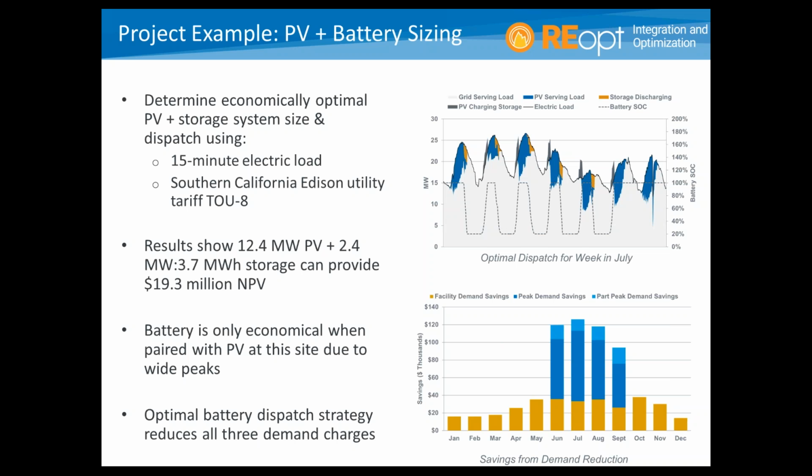So in this graph up here on the right, you can see that early in the day, PV is meeting a lot of the load on its own and can shave the peak on its own. But then later in the day over here on the right, the storage needs to fill in to continue that peak demand shaving. And so they're really effective together because PV can meet a lot of the demand for a lot of the day. As PV starts to trail off at the end of the day, the storage kind of fills in on the shoulder here. And so this is where we get the full peak shaving. And at this particular site, the demand charges are different throughout the day. So we're actually shaving PV to different levels. So there's one period here where the load is getting shaved to this level.